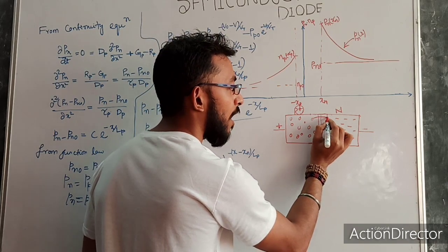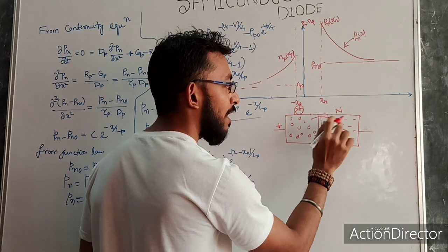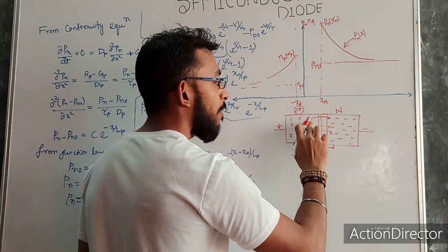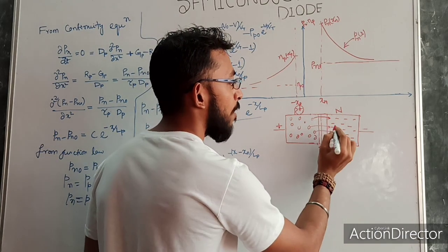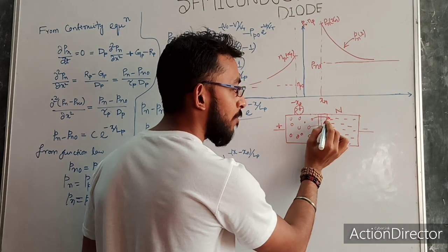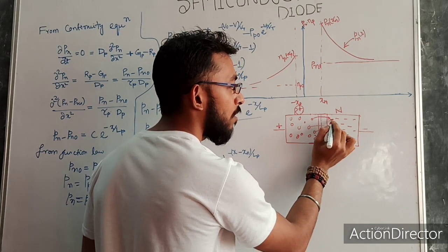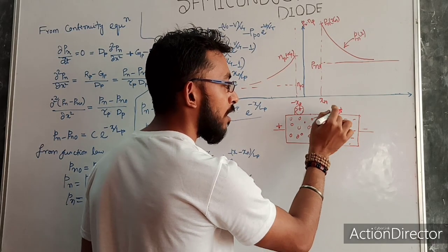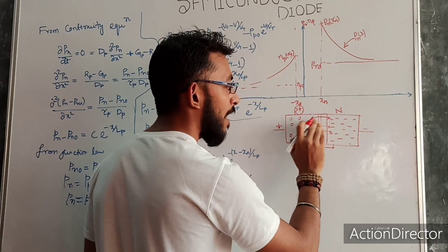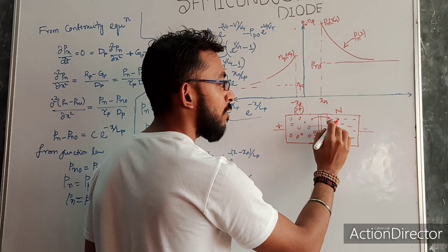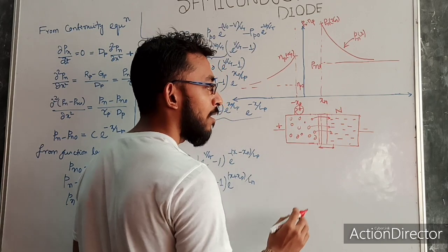As the depletion width is less, there is less barrier and less resistance. So electrons start to diffuse through to that side. If electrons diffuse to that side, what will happen? Here is one electron, here is one hole. The hole starts to diffuse and recombines with this electron, so they disappear. As holes go to the N side, the majority charge carrier electrons there will disappear.